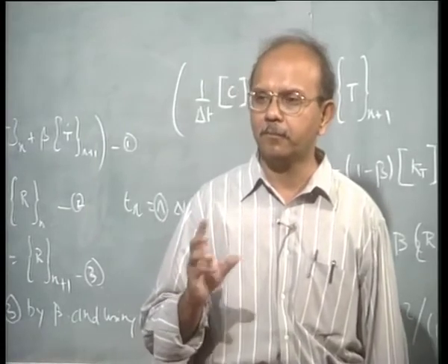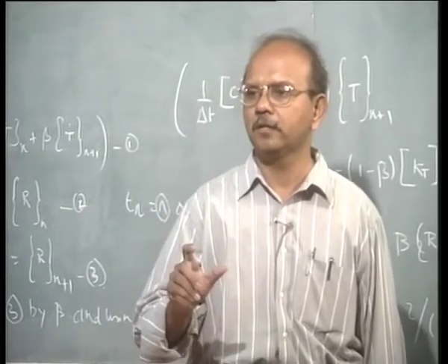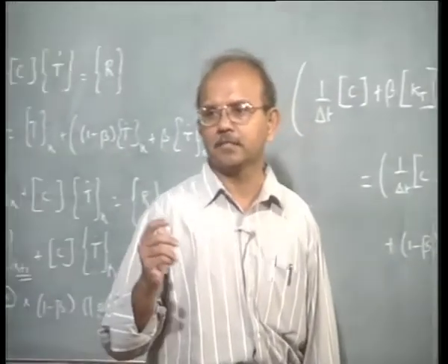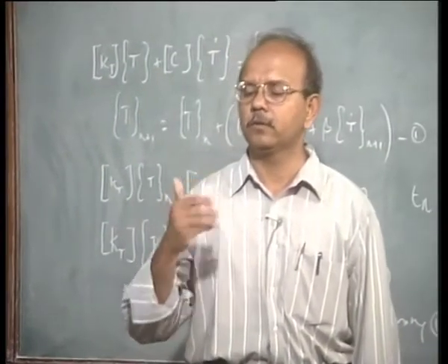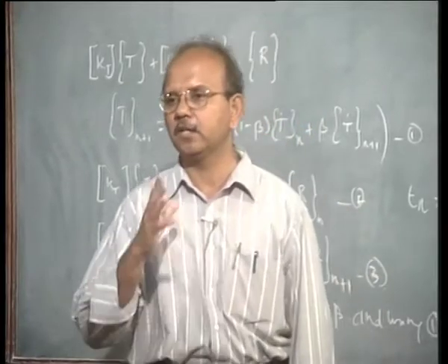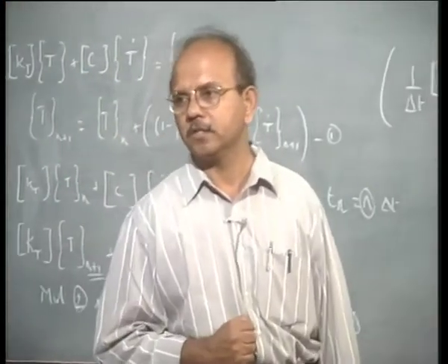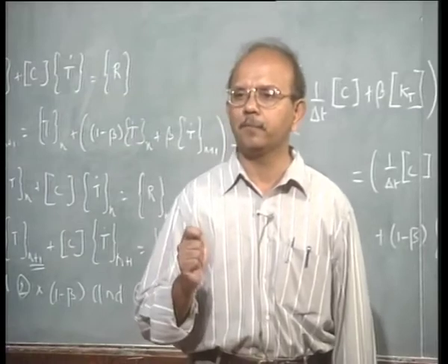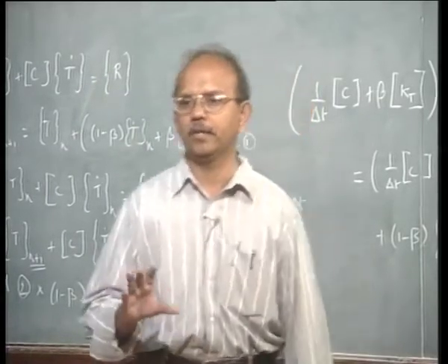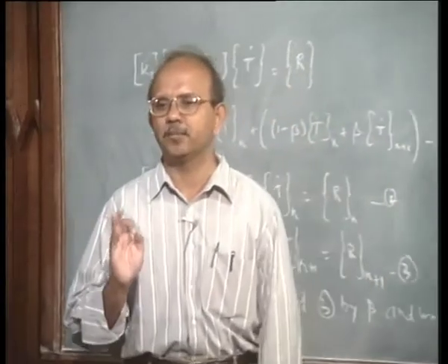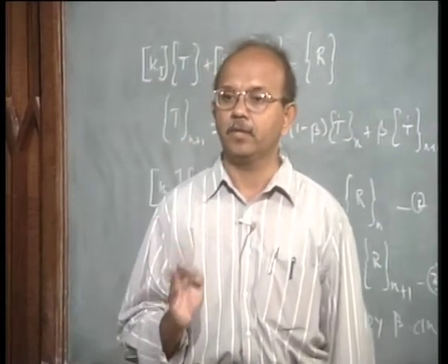We have done plane strain, plane stress, solid. Now, I want to introduce the axisymmetric element to a much deeper extent than what we have studied previously. So, I want you to develop a B matrix and so on, k t and so on, for an axisymmetric element. Attempt it.